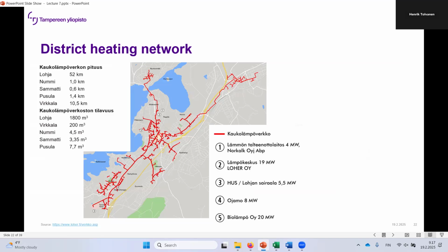And this is an example of a district heating network. It kind of has an analogy to an electrical network as well. So something is being produced, something is flowing, you have customers at the end, there's transmission, there's distribution. But in here, there's no voltage to drive it. So it's the pressure difference that's driving the flow in there, and not the voltage difference.